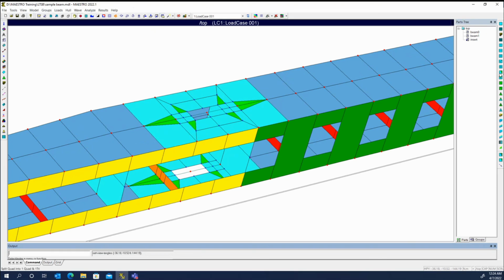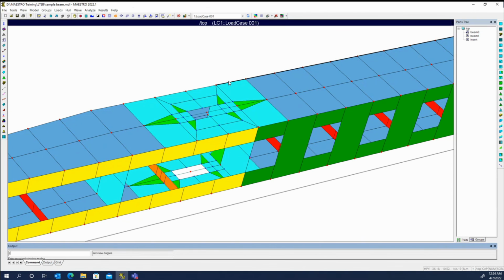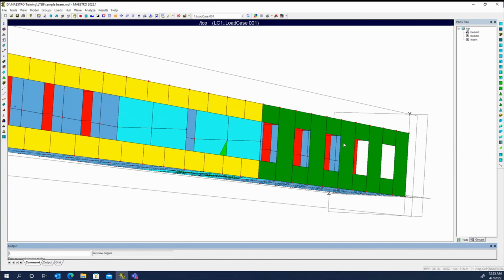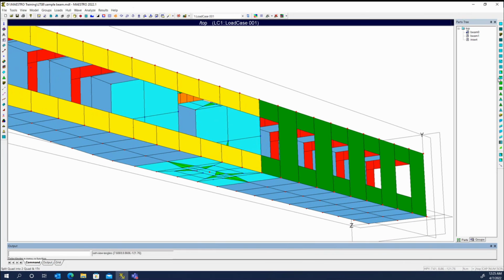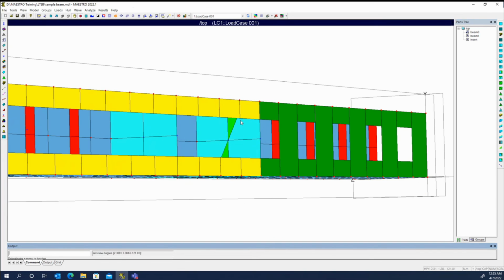For the elements, we would simply do the split again. And this one's facing the wrong direction, so we can flip the normal. When one of these refinement buttons is active, it becomes very difficult to rotate the model. So you'll either have to hit the escape key, or you can hit the cancel button to cancel that operation, spin the model around, and then select it for continuing. So 2 of them were in the right orientation.